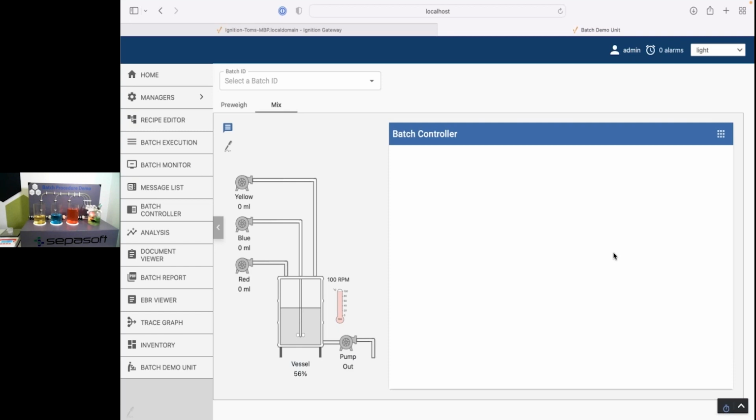It's agitating and it's heating. We see the red light back there. We also see the graphic on the screen is reflecting that. Agitator's animated. So again, this is all in the same system. We don't have a separate HMI SCADA system and a separate batch system. We also are consuming materials. We're seeing that as well. And it will do the pump out. And we see the pump animated there, just simply by binding to a tag.